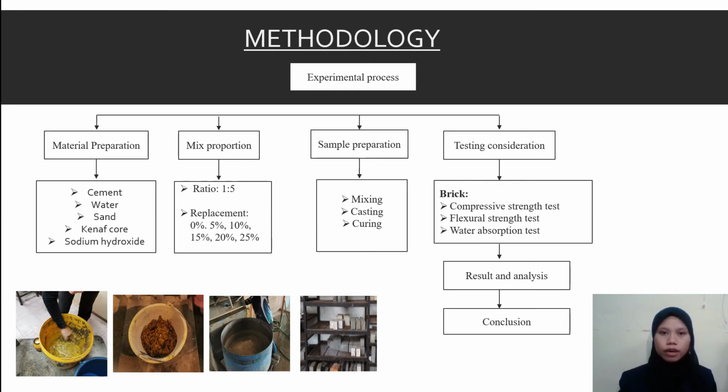For curing, we have different ages, which are 7 days, 28 days, and 56 days. And the testing considerations involved are the compressive strength test, the flexural strength test, and lastly the water absorption test. After that, we can get the results and do analysis from the results.